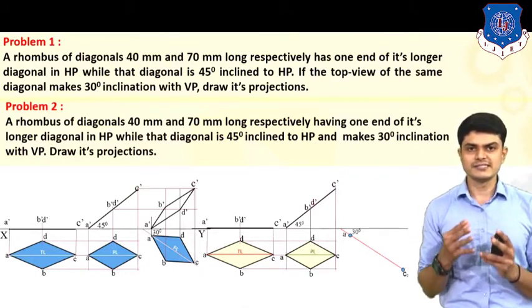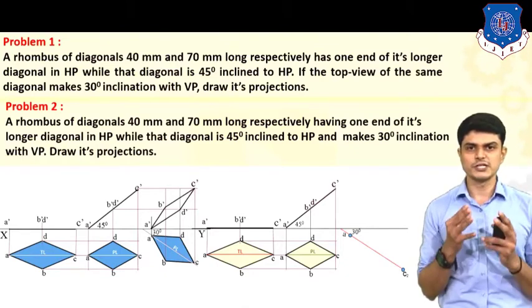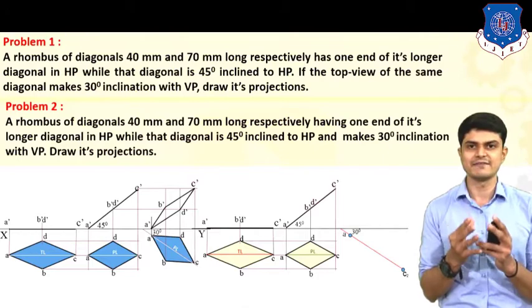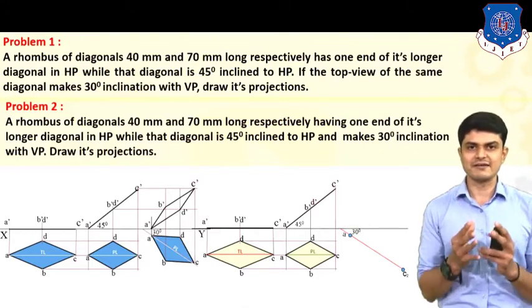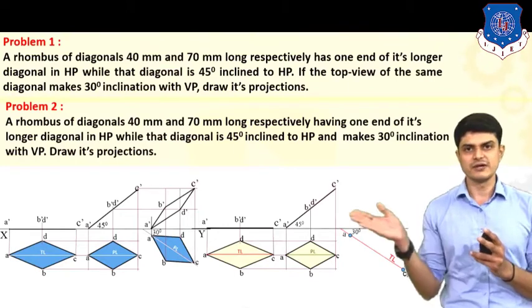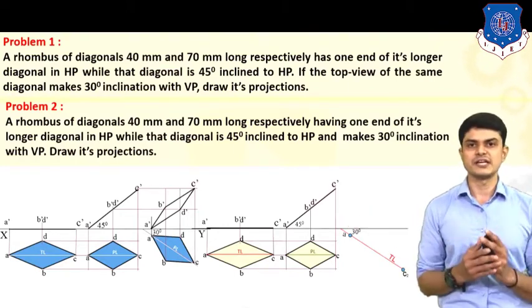Now, this is point C2. Why? Because we will be using the projection of point concept. So when we are drawing the true length, we should identify this point as C2. After having this C2, we have this length as the true length. As you can see, we have taken this length from your first stage drawing.